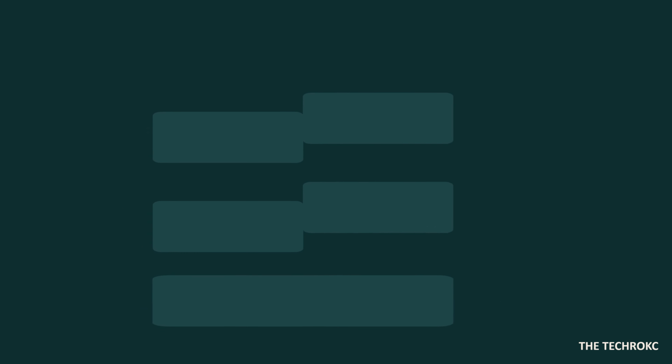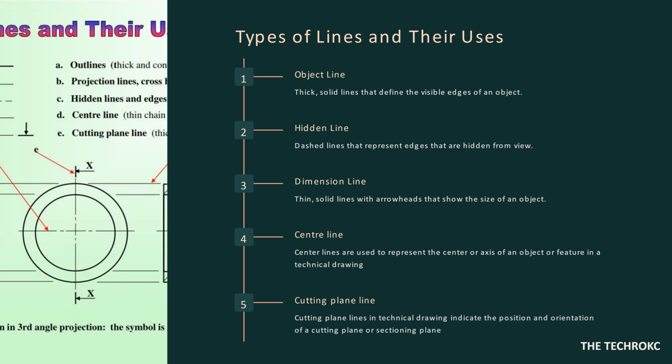Moving on, I'd like to talk about the types of lines we have in technical drawing. There are 5 main types of lines in technical drawing. We have the object lines. They can also be described as normal lines in different textbooks or manuals. They are thick, solid lines that define the visible edge of an object. Mainly, they are the outlines of an object.